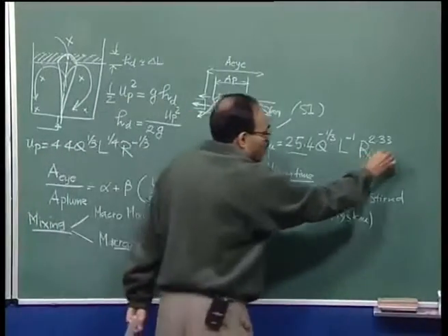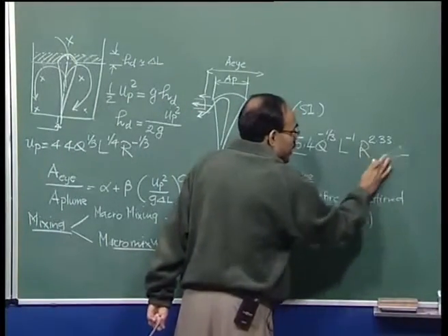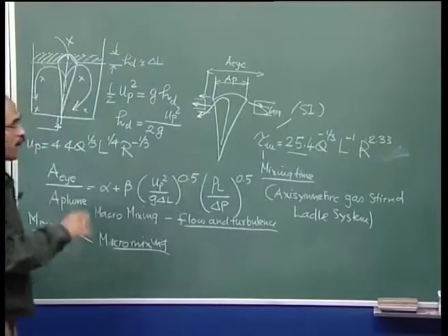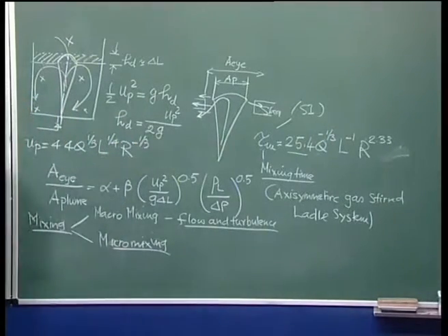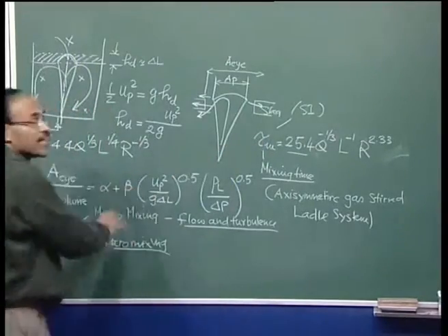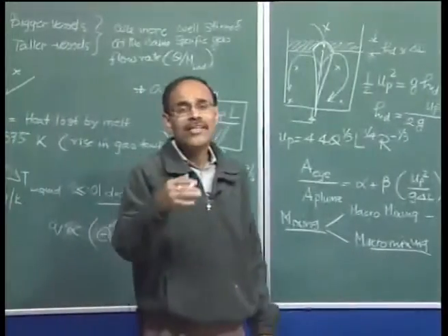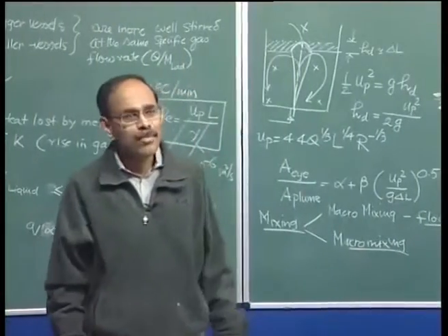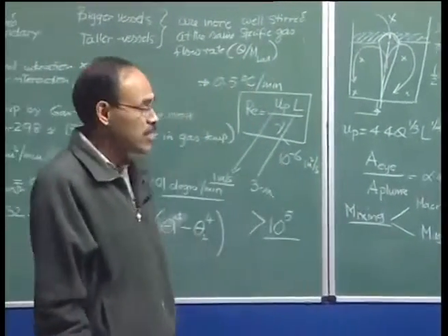You see, I do not have any parameter like this. So, in the absence of any slag, this is the correlation which people have found to work. Again, I repeat that these sorts of correlations are derived from model studies, because it is so difficult to carry out high temperature experimental observations in steelmaking operations.